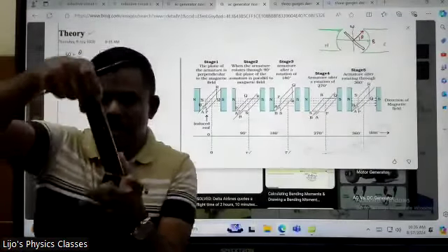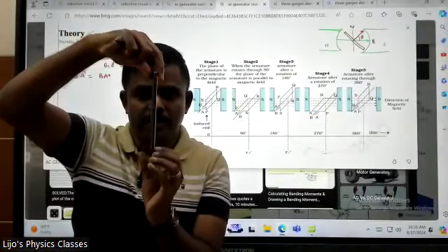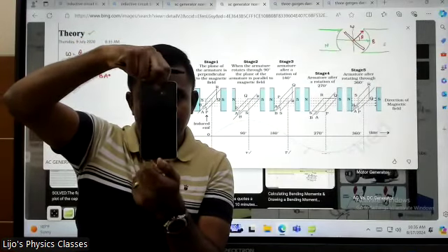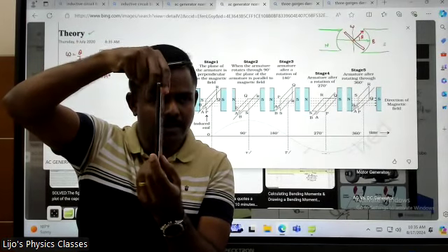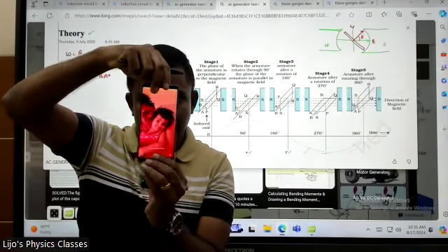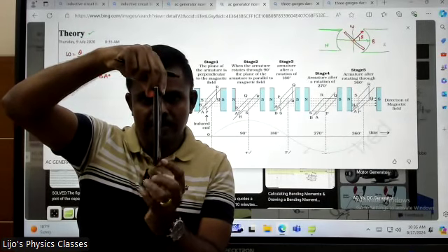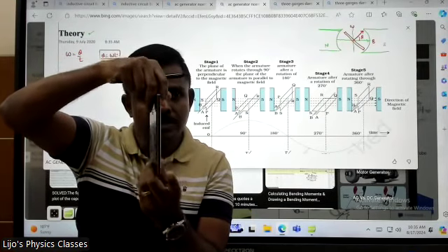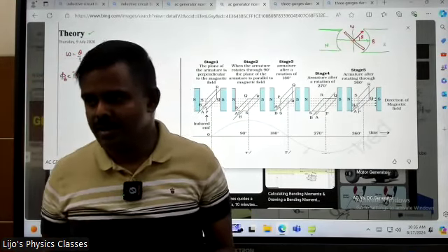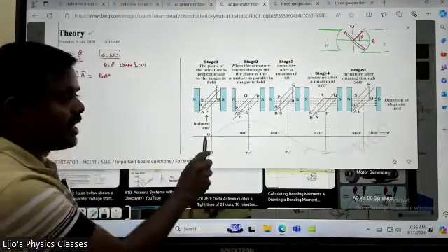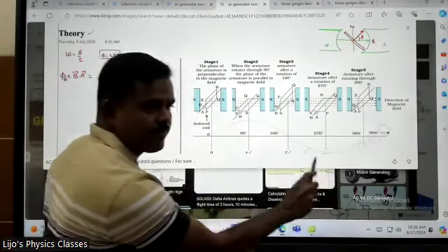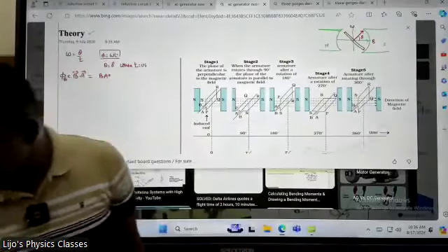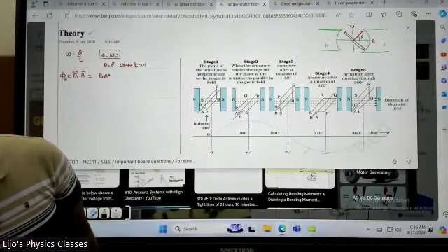Look at this. This is the coil. Coil is initially perpendicular, 90 degree, 180 degree, 270 degree, 360 degree. Got it? Which is counted as 0. Again 90, 180, 270, 360. How many times? 50 times in a second. Got it? So you are getting electricity continuously this way. I'll show this mathematically in the next class. Okay? That's all. Shall we wind up for the day?